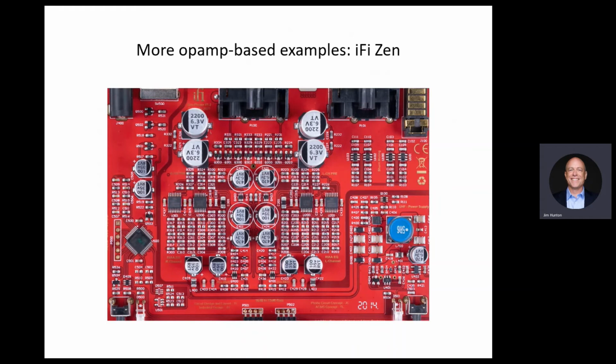Now they need higher voltage because they made a decision to use very new, very low noise, very low offset op amps. So the solution is a switch mode power supply running at 1.2 megahertz. They claim that because of the high frequency, it's easy to filter, so very little noise goes into the circuit.